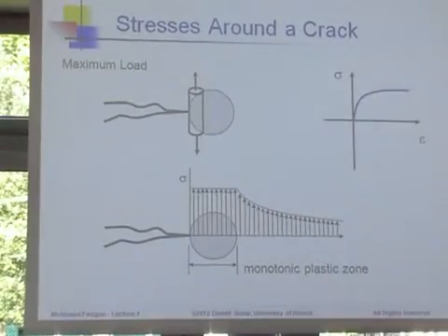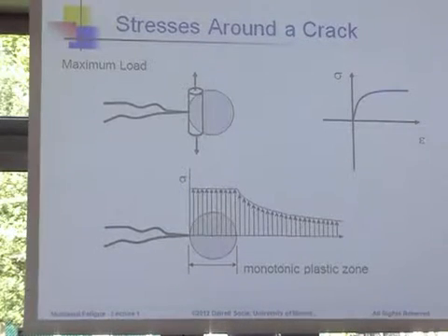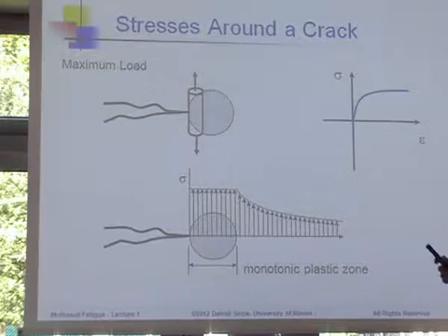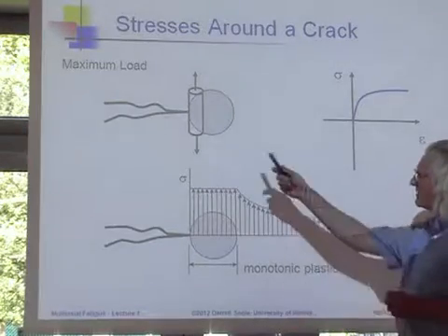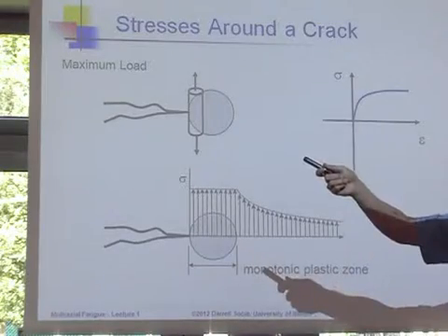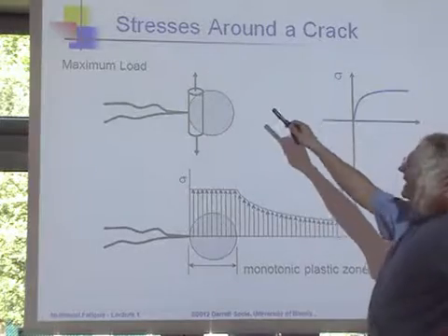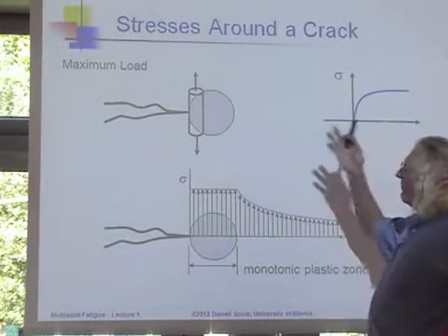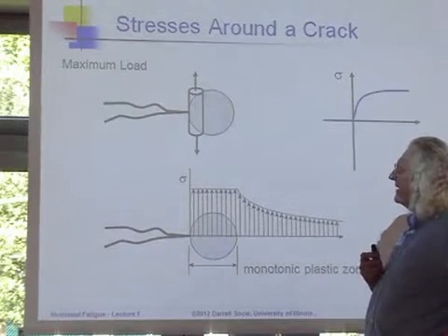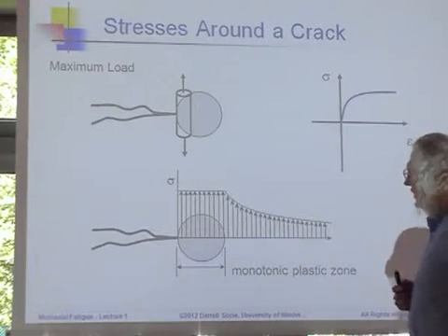Last thing, I just want to show us a little bit about the stress fields around a crack. To help me visualize, I think of a crack, and you can see I'm a little more creative with my cracks. I don't draw them with straight lines, for the reason I told you. I don't see them at that size scale over there. And I have a plastic zone there, and I'd like to know what happens in terms of the stresses and strains around the crack. And so just to help me, I draw my little specimen to help me visualize what happens.